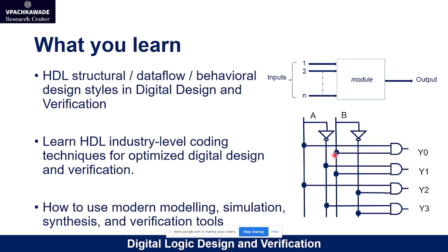On the other hand, there is structural modeling at the bottom. You specifically design and write a code that will implement a structure of the logic. For example, you want to build a multiplexer. Then you will decide as a designer whether you want to build that multiplexer using transmission gates, simple pass gates, or simple transistor logic.